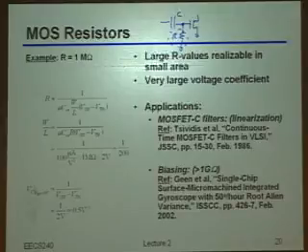Okay, a bunch of you guys are shaking your heads, so I guess a bunch of you do indeed believe in quantum mechanics. And the answer is indeed that current is probably not really 0. Because when you get that thin of an oxide, electrons can literally just tunnel directly from the gate into either the channel, to the source, to the drain, and indeed, you will see non-zero currents flowing through that gate there.